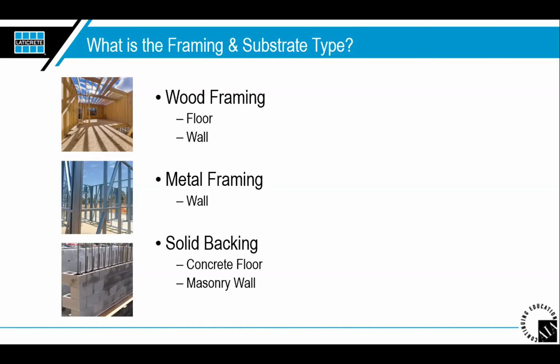Exterior concrete walls, so that's the last part of this: they must be clean, they must be plumb and true, right? We can't set stone on walls that are wavy, and a lot of times we want them waterproof prior to the installation and stone going over top of them. That's so we don't allow any water to get back behind the installation and do any type of wicking. For example, if you're doing natural stone ledger on a stone wall, you don't want the water itself to come through and start wicking up and maybe even change the look of your natural stone.